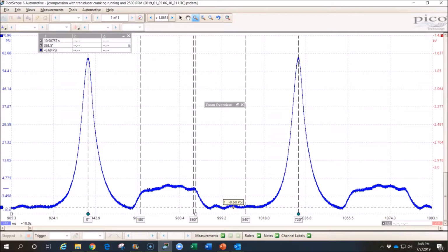And to convert that, just as a rule of thumb, you can double your psi reading to get inches of mercury. So that's around 16 or 17 inches of mercury of vacuum, or lower than atmospheric pressure that we have in our intake manifold at this point. So again, we don't see any changes in pressure because the valve is open as the piston is going down.